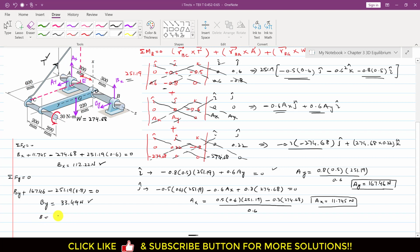So the resultant reaction at point B will be equal to Bx square plus By square under the root. So we can write that this is 112.22 square plus 33.49 squared. We will take the square root, and similarly the resultant reaction at point A will be Ax square plus Ay square. So Ax is 11.745 squared plus Ay, which is 167.46 squared. So the reaction at A is 167.87 newtons and the reaction at point B at bearing B is 117.11 Newton. So this is the solution of this particular problem.